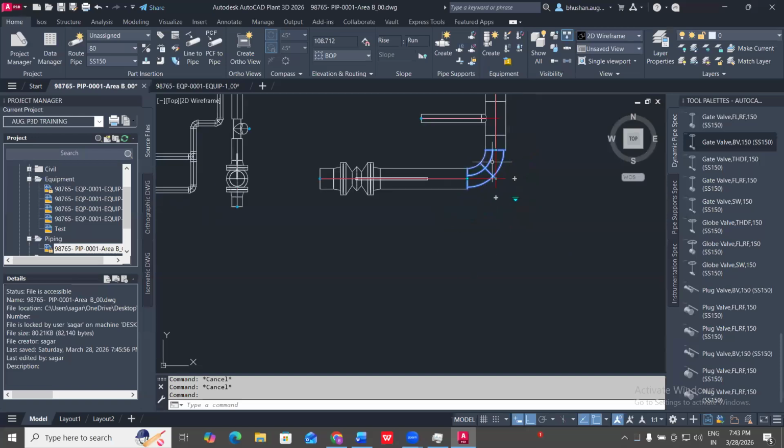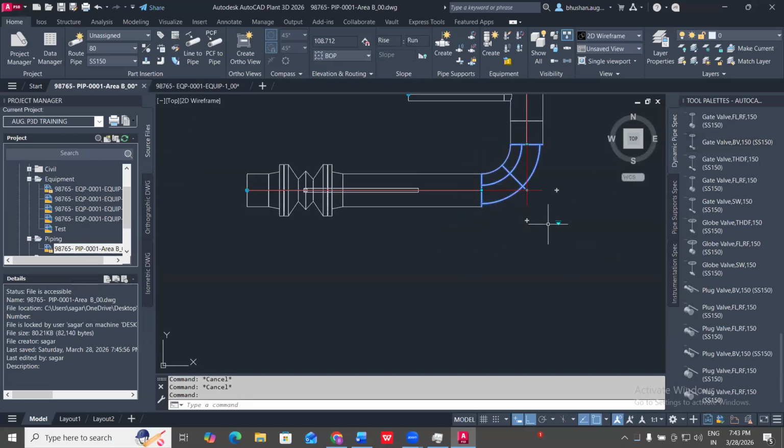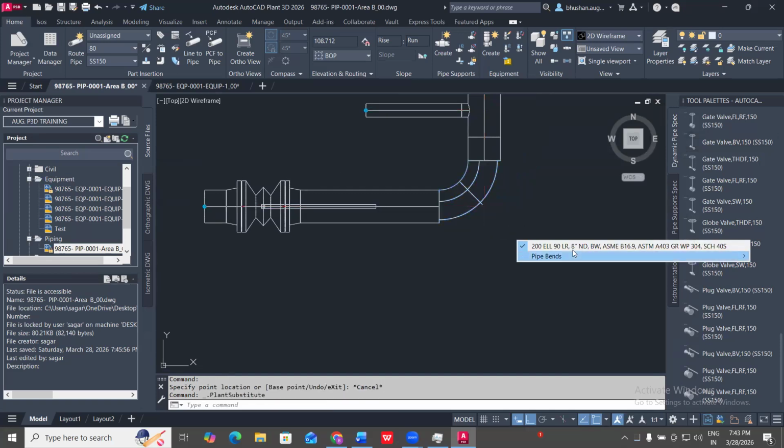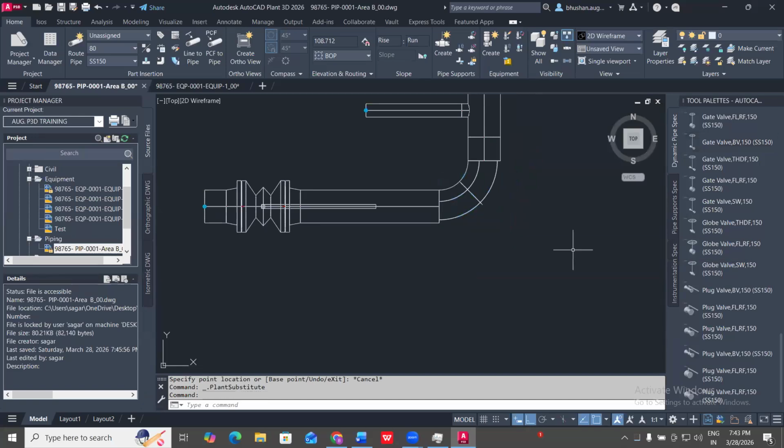When you want to add it, you will not be able to add a T here, because this bend is a different part which you have added. If you have seen the pipe spec document or any document, you should know that an elbow is a different fitting and a T is a different fitting, and both fittings have a different purpose or application, right?